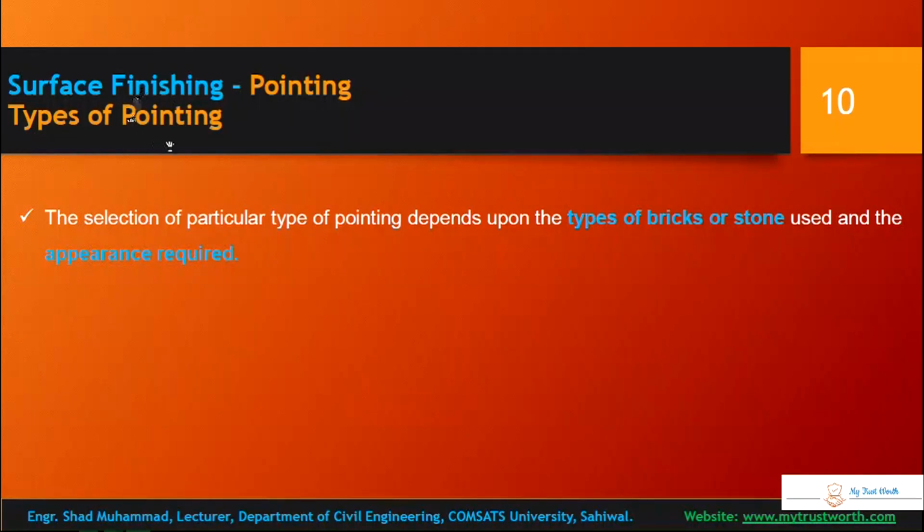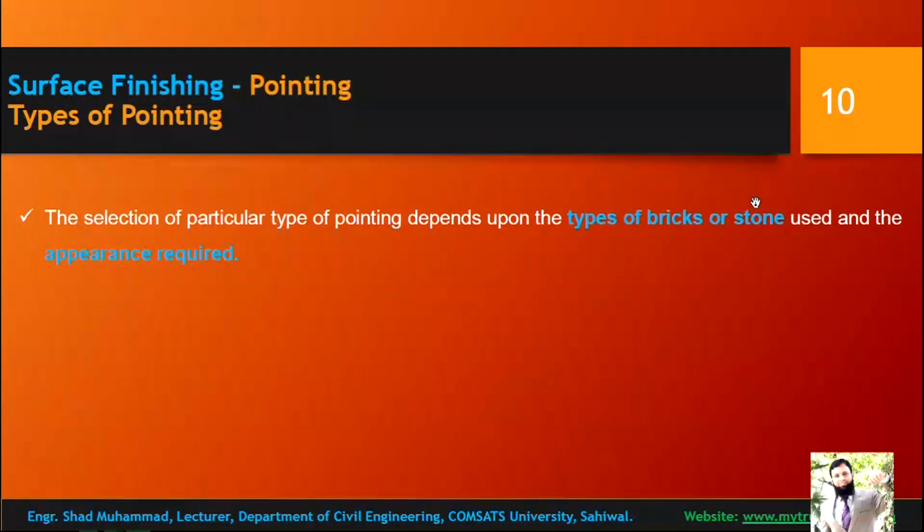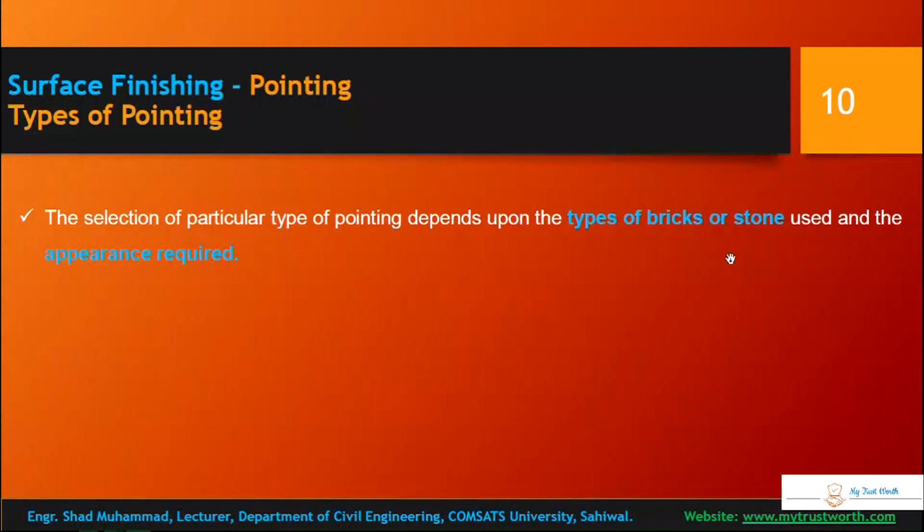That's necessary, because when you are plastering stone masonry with bigger stones, the bonding of the mortar with the stone will not be enough, and it will not have an adhesive effect. Although you provide artificial keys by engraving the stones, that won't perform well. And appearance required. All right,